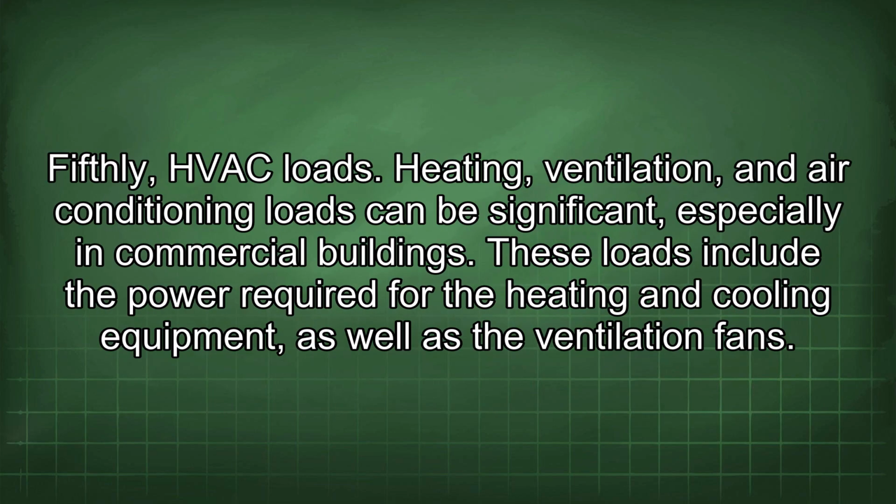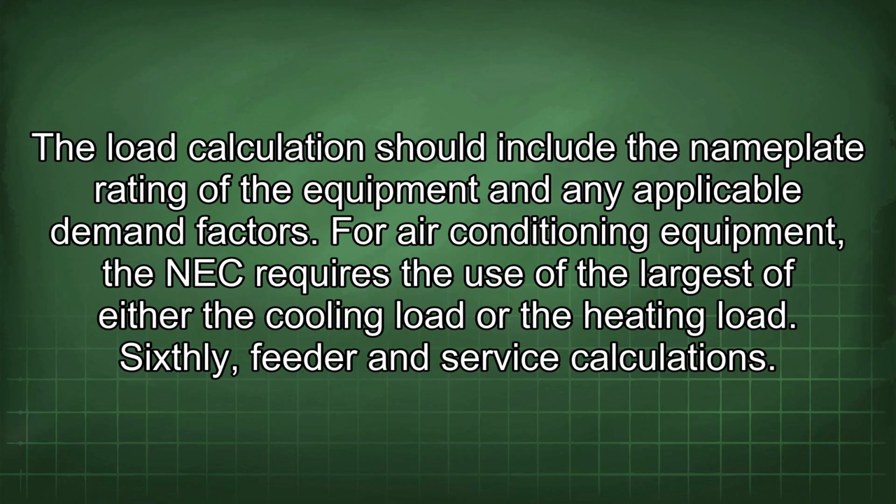Fifthly, HVAC loads. Heating, ventilation, and air conditioning loads can be significant, especially in commercial buildings. These loads include the power required for the heating and cooling equipment, as well as the ventilation fans. The load calculation should include the nameplate rating of the equipment and any applicable demand factors. For air conditioning equipment, the NEC requires the use of the largest of either the cooling load or the heating load.